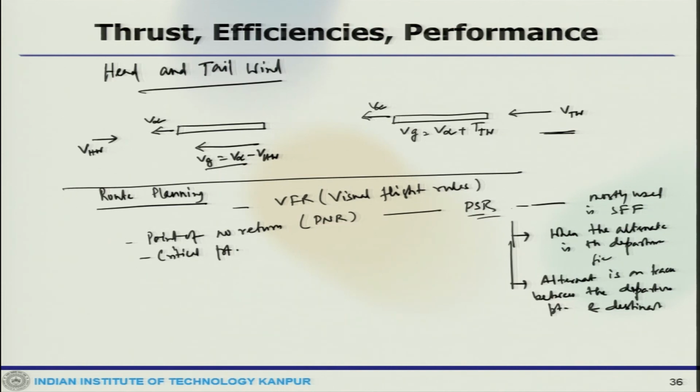So, this is how point of no return or PSR is accounted for, and the other one is the critical point. Similarly, the equal time point, referred to as ETP, also critical point, is the point in the flight where it would take the same time to continue flying straight or track back to the departure aerodrome. ETP is not dependent on fuel, but on wind, giving changes in ground speed out from and back to the departure aerodrome.